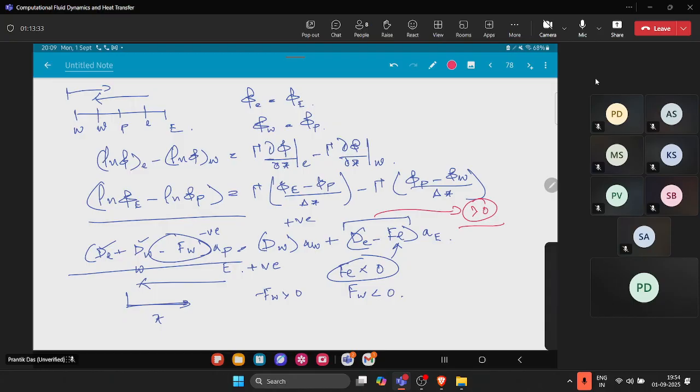As we said earlier, transportiveness is one of the things violated in the case of the central difference formula. So what we did was tweak the formula in such a manner that transportiveness is obeyed in our case. So we may hope that this is something we should always obey. But there are some problems in this case also, which we are going to discuss subsequently. I hope I'm clear until now. Am I clear until now?